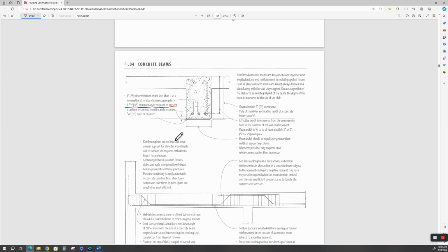Concrete on grade, like the footings in the previous videos, we said needed a minimum of 3 inches of cover. Wastewater treatment systems, we want 3 to 4 inches of cover, because we're also going to apply some kind of coating barrier on the clarifier walls and the sludge digester walls that are made out of reinforced concrete. All right, but for general structural concrete that's not exposed to the ground, you want at least 1.5 inches.